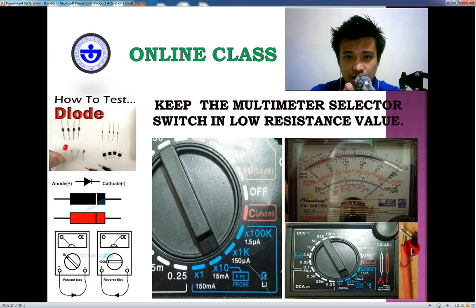By connecting your two test probes, your needle pointer will move towards 0 ohm. If your needle pointer does not stay exactly on 0, you turn this rotary knob, the 0 ohm adjustment knob, either clockwise or counterclockwise, just to move your needle pointer exactly on 0 ohm.